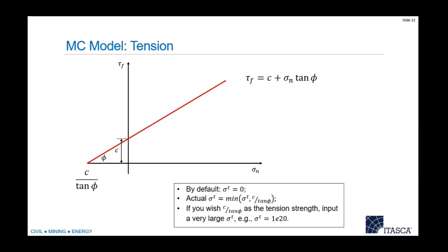The fact that we're doing explicit also makes it relatively easy to write your own constitutive models, like I was saying. Because again, you don't need to work out all these return paths and crazy stuff that they have to do. You just put in the stress-strain relationship and it just follows it along, right? This makes it a lot easier to do these.